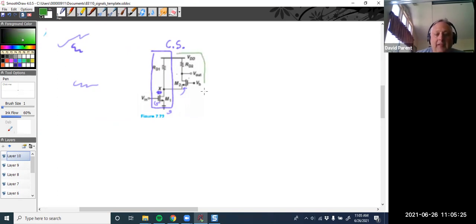And so guessing, that's going to be some kind of common gate, right? And again, intuitively, Vout over Vx is going to be inverting. And if I recall off the top of my head, common gates don't invert, and so it would be non-inverting. So inverting times non-inverting, I should get some kind of minus sign there.